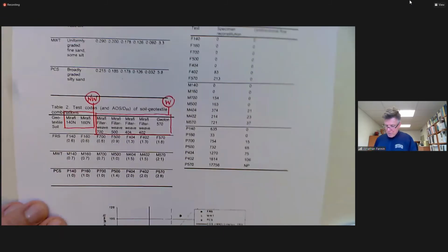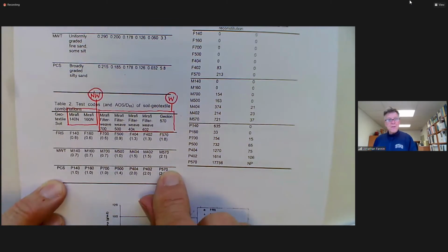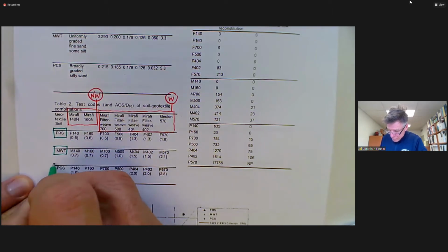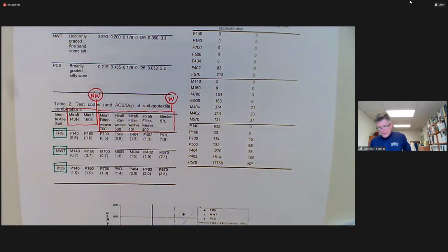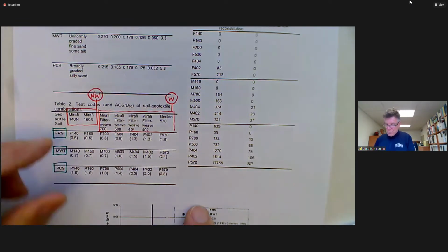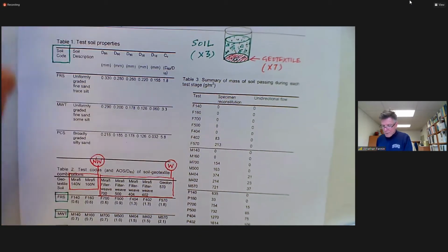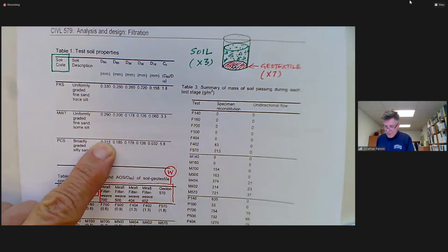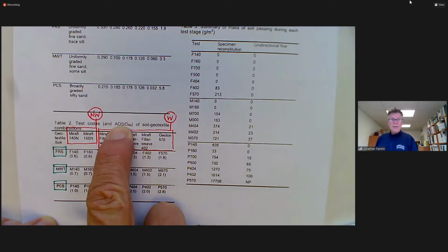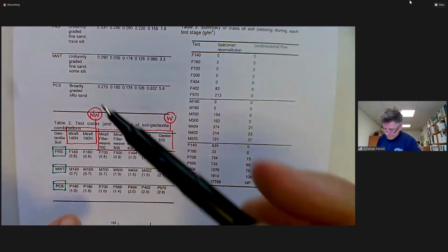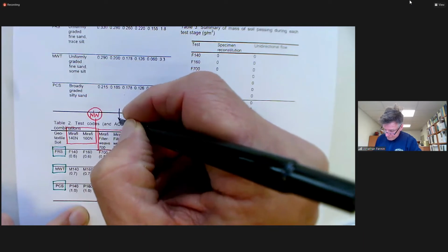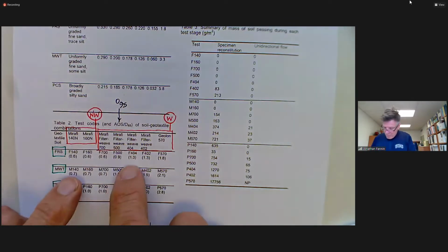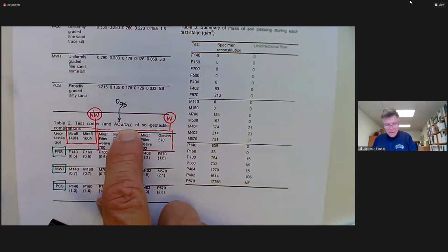So that leads to a 7x3 matrix. There are the 3 soils. Let's look at the soils. The mine waste tailings, the Port Coquitlam silty sand, and the combinations informed by, for example, the D85 of those soils, and informed by the apparent opening size, or O95, of the geotextiles, we end up with a ratio AOS to D85.